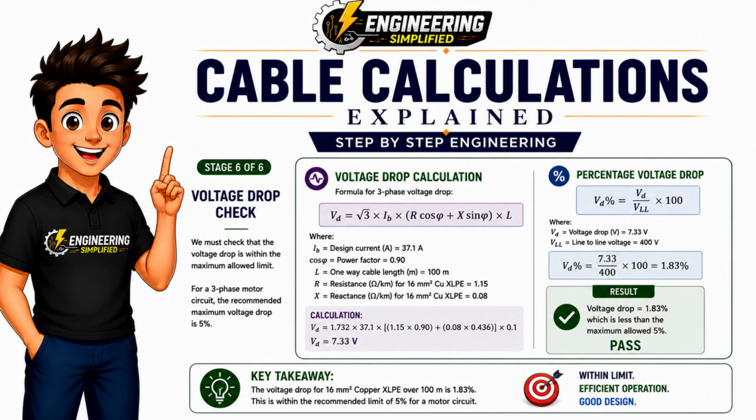For this installation, we're supplying a 3-phase motor, so we'll use the standard 3-phase voltage drop equation. The calculation takes into account the design current, the cable length, the cable resistance, the cable reactance, and the power factor of the load. By substituting our project values into the equation, we calculate a voltage drop of 7.33 volts.